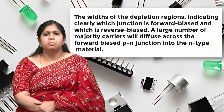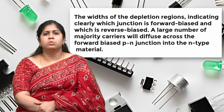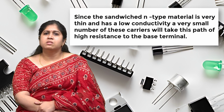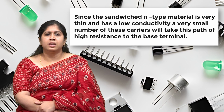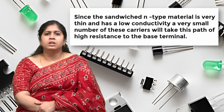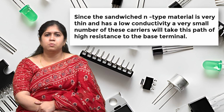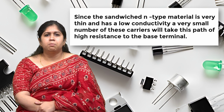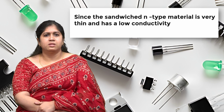A large number of majority carriers will diffuse across the forward biased PN junction into the N type material. Since the sandwiched N type material is very thin and has a lower conductivity, a very small number of these carriers will take the path of higher resistance to the base terminal.